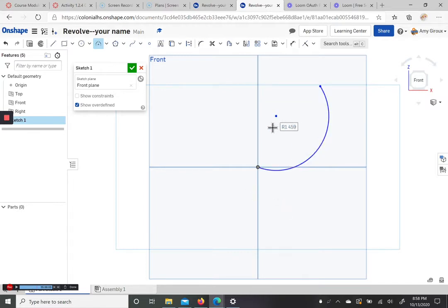So if you notice, our value here for our radius, so R is radius, is in that little box still. So that means we can just type and it will automatically change this value. So we're going to type 2 for our 2 inches, since that's our default unit. If you notice, this little dot is pretty far away. Remember, we need to hit Escape or click on our tool, or right click and Escape to get that off of our cursor.